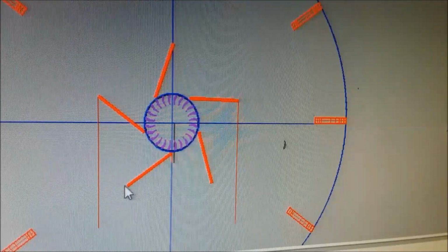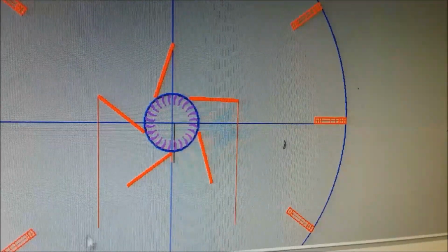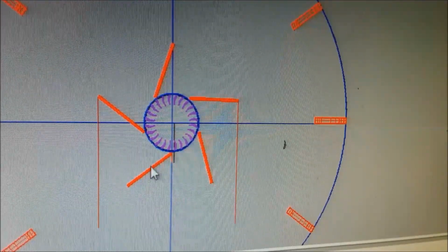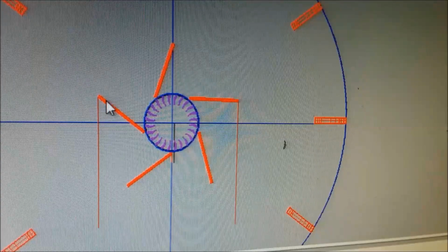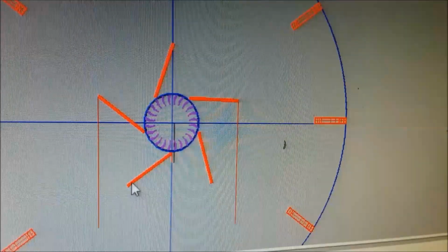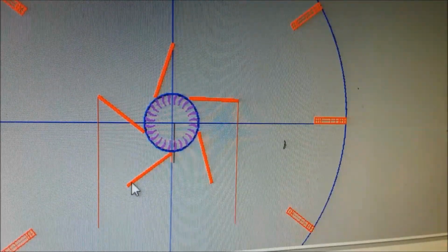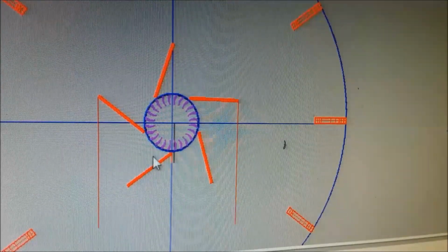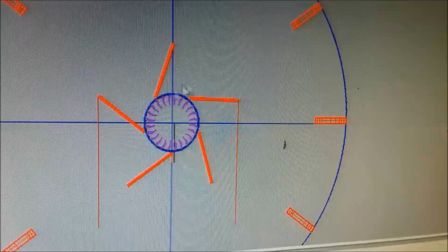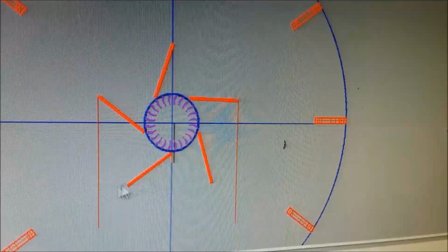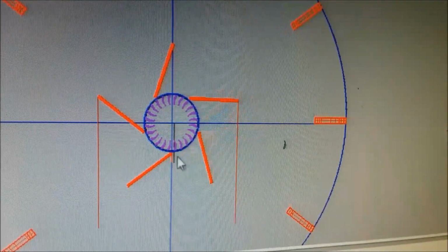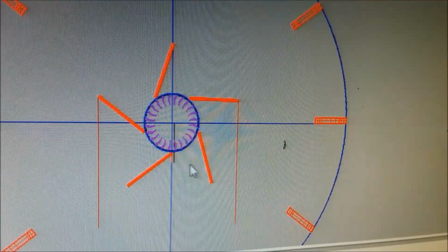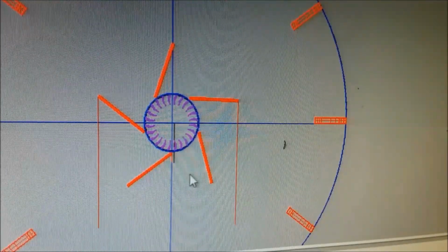But this one vane redirects any air that they want it to redirect, and this thing has to rotate around just on bearings, just like the tail on a horizontal axis wind turbine. They just put this big plate instead of a tail. But it's a geared motor that drives it, because the wind would try to blow it the wrong way as soon as it hit it. But they're using that to boost the air through the turbine, and they're getting about 3 times the power out of it with it as compared to without it.